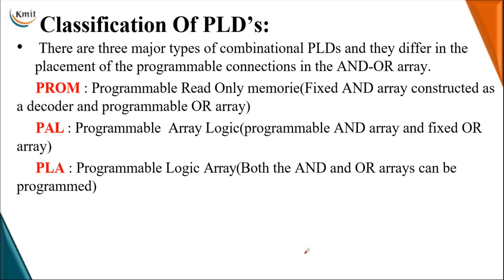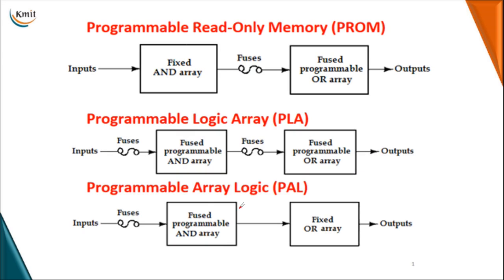PAL is a programmable array logic. In this programmable array logic, the inputs of the AND gates are all connected with programmable fuses or links, and the OR gates are fixed. In PLA, which is abbreviated as programmable logic array, both the AND arrays as well as the OR arrays are programmable. Now let me deal with PLA in today's session. After this PLA, we will move to PAL, as we finish PROM, so we will move to PLA.